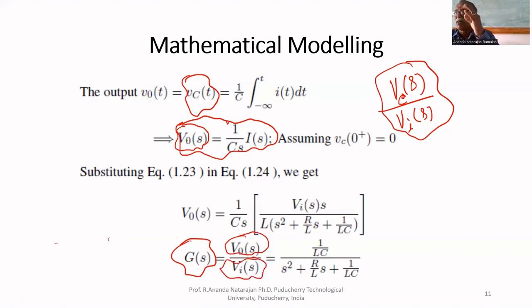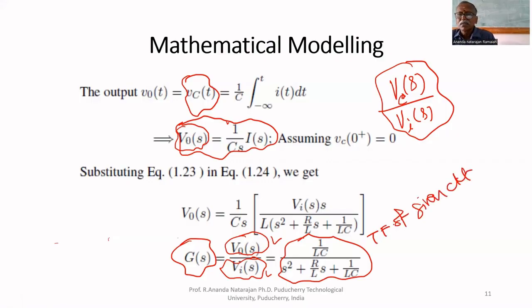The input voltage applied to the circuit. What is the definition for transfer function? Laplace transform of output upon Laplace transform of input. That we got. That's why this is the transfer function of the given circuit. In other words, the mathematical model of the system in the Laplace domain, or in the frequency domain, or in transfer function form. All are the same.